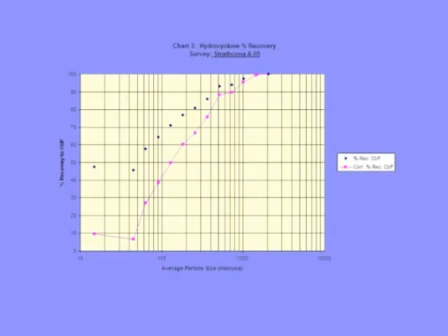Here's the initial survey cyclone performance curve, and this is the reduced curve, and we did some test work with a new modern cyclone. Watch what happens up in this region. It's essentially the same D50C, and we got rid of a lot of coarse particles. The overall sharpness of separation improved significantly.